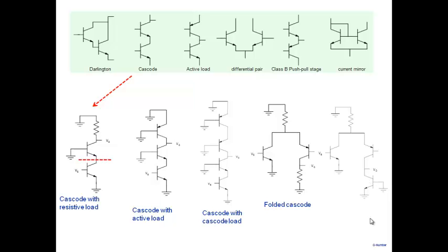Okay. I could take one more transistor and put it down here as well. So you can do all of that. And note that at any point, what I can also do is take this transistor out and replace it by a Darlington to build a high input resistance here. So I can do that also. I can take it here and put it over here. All right. So one of the ways of generating new amplifiers with new characteristics is to take the existing elements that are there, connect and combine them, and then you will generate new stages with new properties.